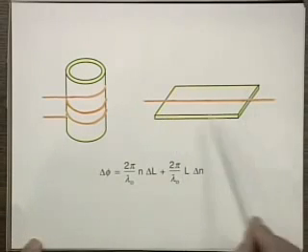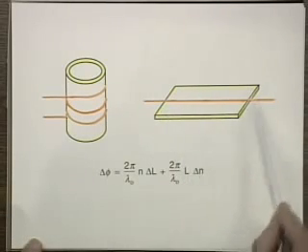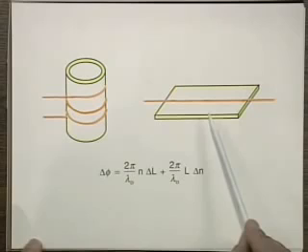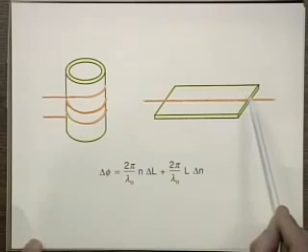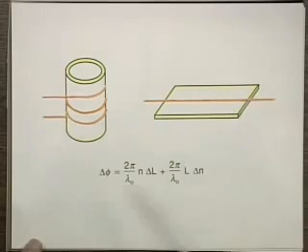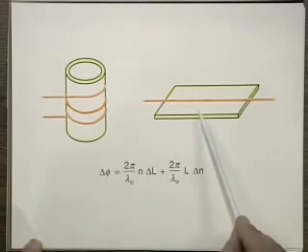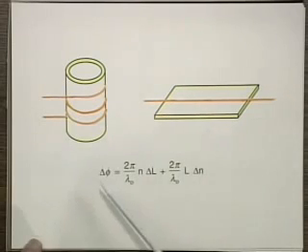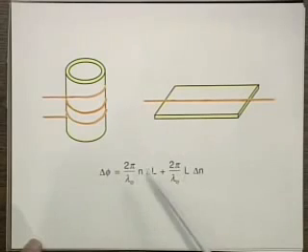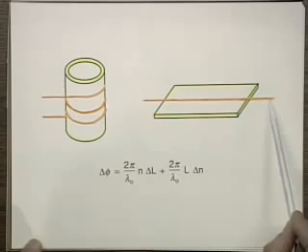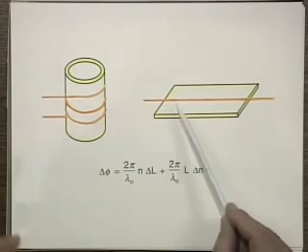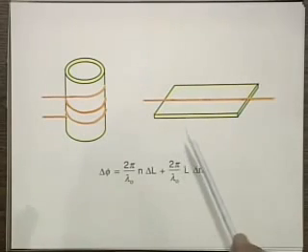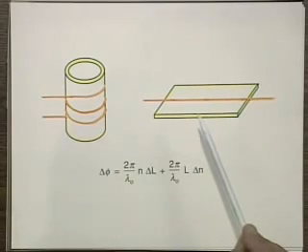Another type of piezoelectric device is a sheet. It is a piezoelectric strip or sheet where the fiber is just attached to, bonded to this. You don't have to bond it that rigidly to this sheet. And then by applying a voltage between the upper and the lower surface, you can again stretch the fiber, and then you can essentially modulate the light that's propagating. So that's a very neat way. You don't have to break the fiber; it's still intact, and you can get phase modulation.